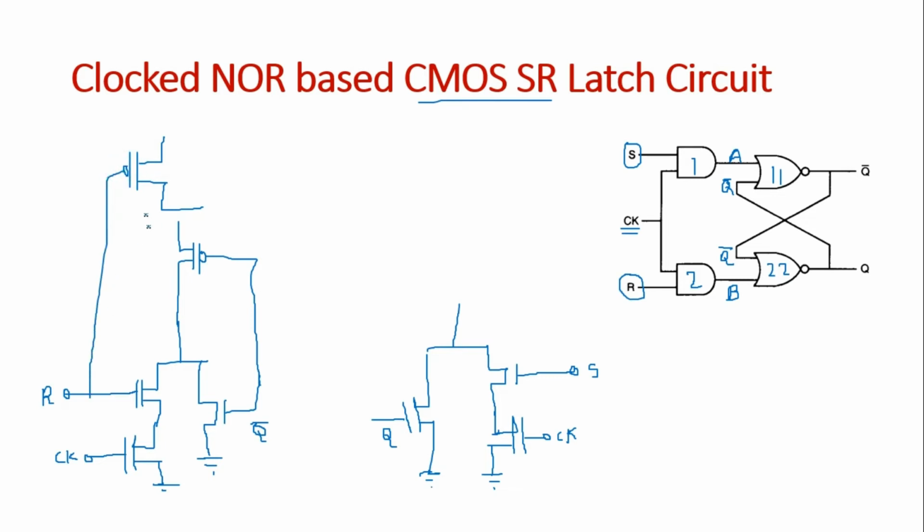Okay, and then parallel connection means we will draw a clock over here. So this is our clock signal. Now you can see that this R and clock are in parallel over here. Then this full combination is in series with the Q bar. So totally the complement of NMOS will be over here, and we will connect this with a VDD. So this is your VDD.